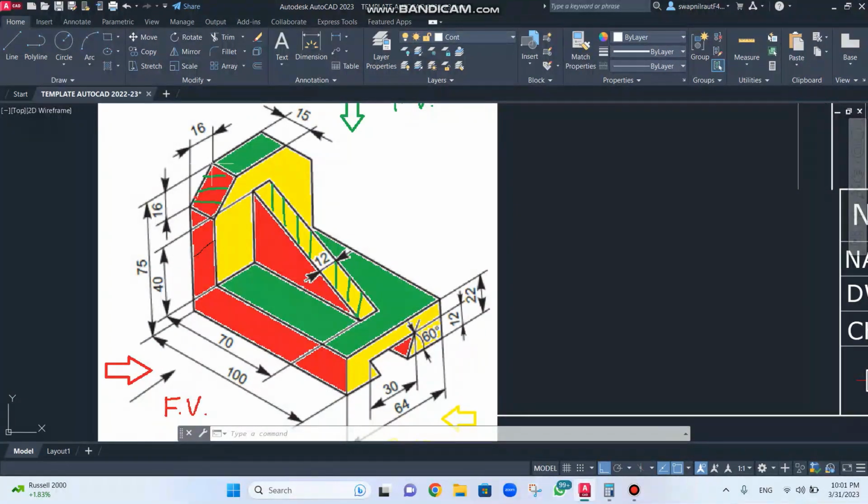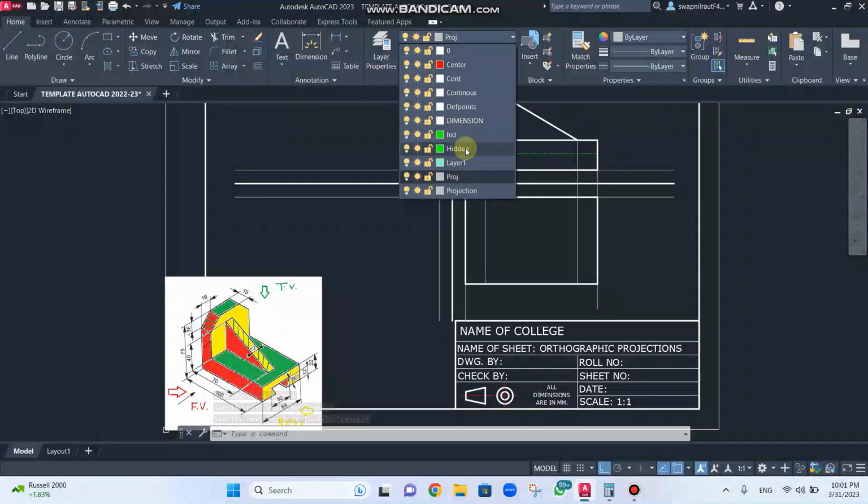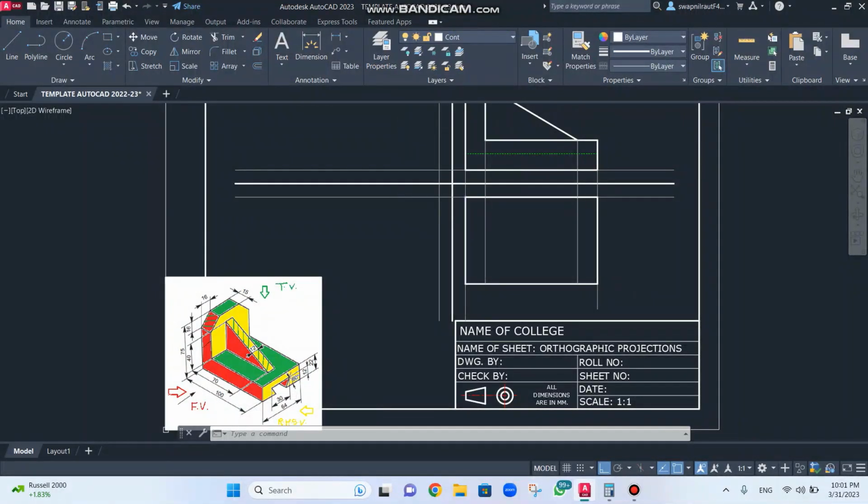Okay, and these two slant edges I need to draw, this first one and this second one. So what I will do is I will take reference. For reference you will use projection line, L, enter. So this is the first reference that I am taking. And then again this is the second reference for the rib. Now this is dark, so I will draw it by using a continuous line. So again I'll enter, this is my dark.